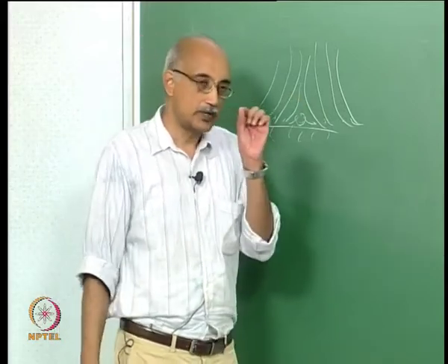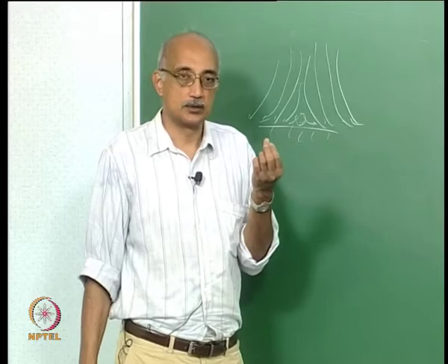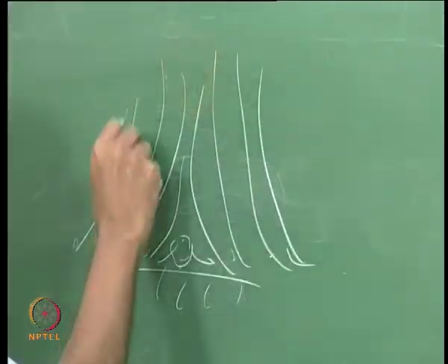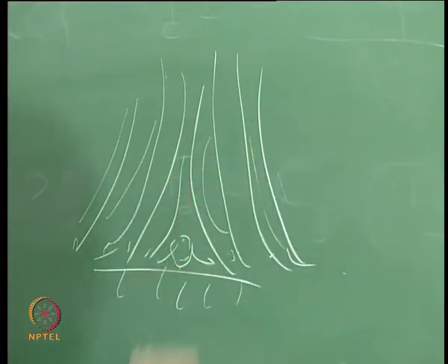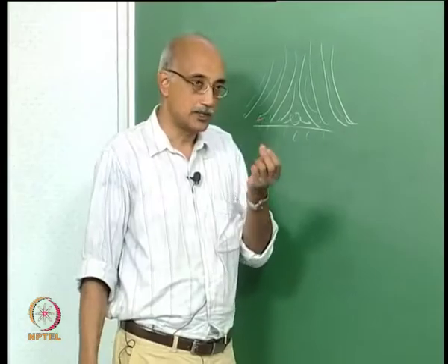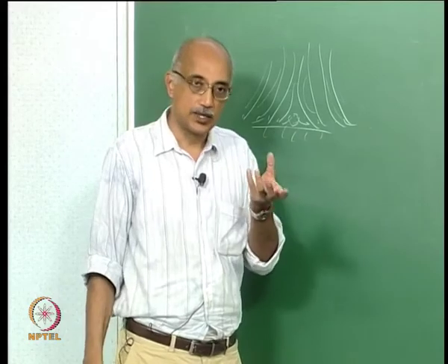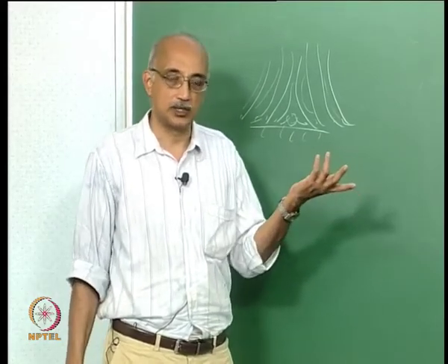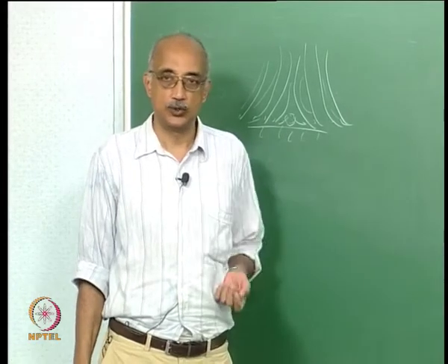So if you have very, very fine particles, let's start with molecules. What would molecules do? They would basically follow the streamlines, right? They will just keep going along with the fluid streamlines. Let's say the particle size gets bigger, gets to the nano sizes. What are they going to do? For the most part, they're going to do the same thing. They're going to keep following fluid streamlines.